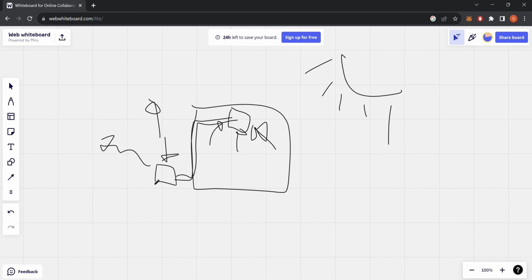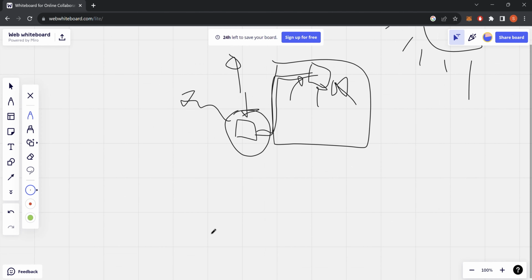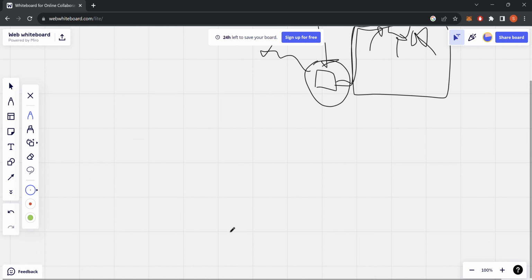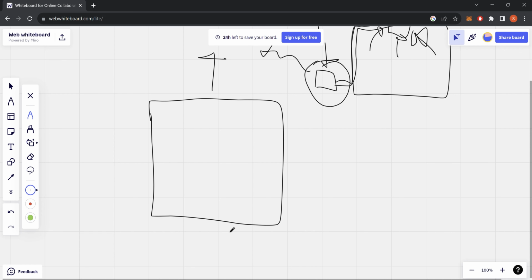So if we take a blow up of this basic premise here, let's take a look at the condenser unit that would be outside. So in our unit, we need two flows of fluid in order to do heat transfer here. So I will draw the airflow. There's normally a fan blowing air up out of the air condenser, right? So air is getting sucked in. Well, it's really getting sucked in through the sides, but we're going to pretend it's getting sucked in through the bottom. So air is getting pulled in and pushed out with a big metal fan. Normally you can look right in the top of your condenser and you see your metal fan, right? So that's one fluid, is air.